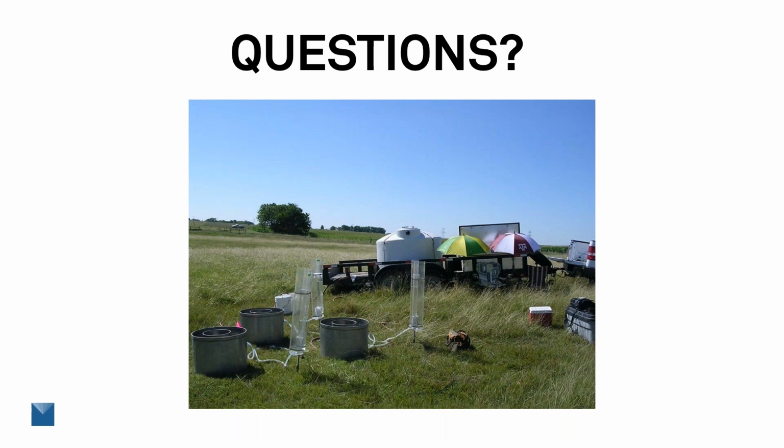So my recommendation is time your measurements when they're not cracked, which is what we tried to do. But if they're smaller cracks, then you can measure directly over them, but you're probably going to see a fairly high infiltration rate.